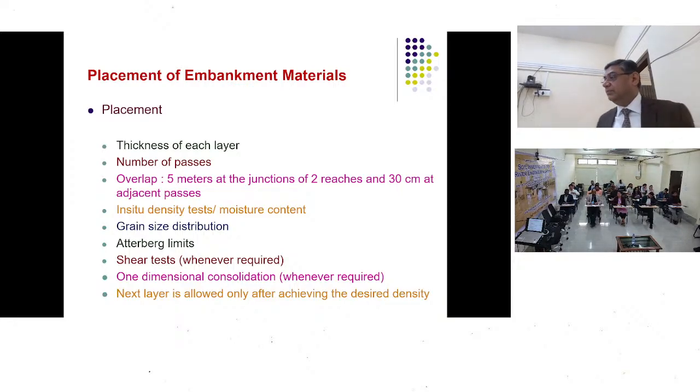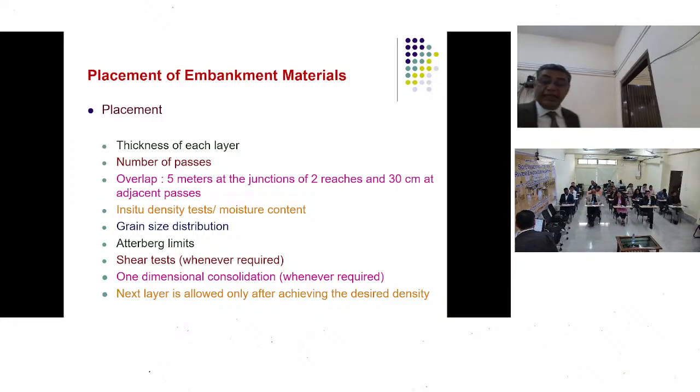This is a long dam. Now you cannot construct it in one part. So you will be having maybe a reach going up to here and then another reach from there. So you will be having an overlap region this way, as well as you may be having adjacent passes. So you will be having an overlap here. So as a quality control, you will be seeing whether this overlap is really maintained or not.